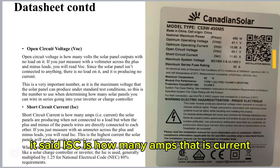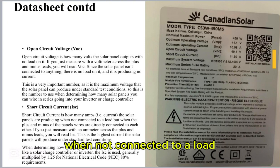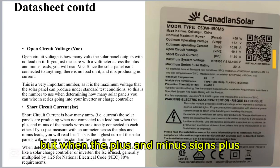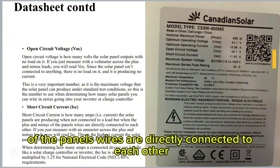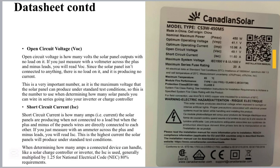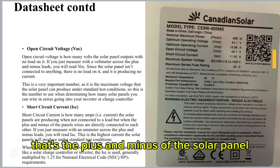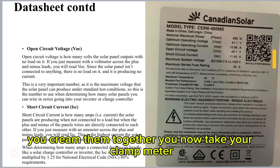ISC is how many amps, that is current, the solar panel is producing when not connected to a load, but when the plus and minus wires of the panel are directly connected to each other. So you take the positive and negative, that's the plus and minus of the solar panel, you put them together, you crimp them together.